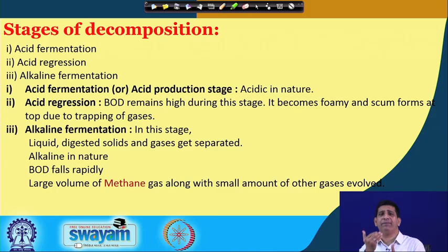So, that part happens in what is known as hydrolysis, where things get made more of a soupy kind of material, much like a milkshake. Like those shakes, things get broken down into smaller pieces, and then our acidogenic bacteria start acting on it and produce what is known as acid fermentation. After acid fermentation, we finally have acetic acid, and after acetic acid you will have methanogenic bacteria, which will convert this acetic acid to methane, like biogas, and that's how the reaction takes place.